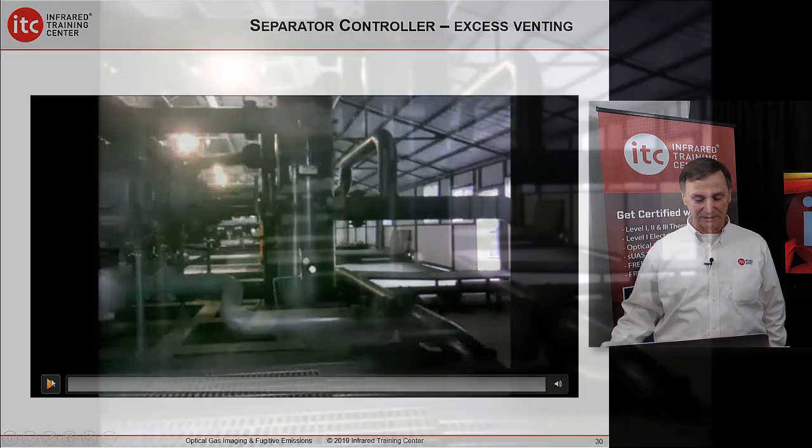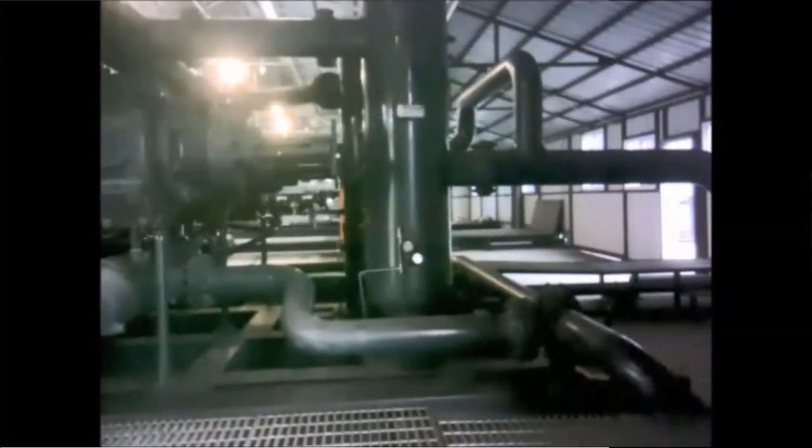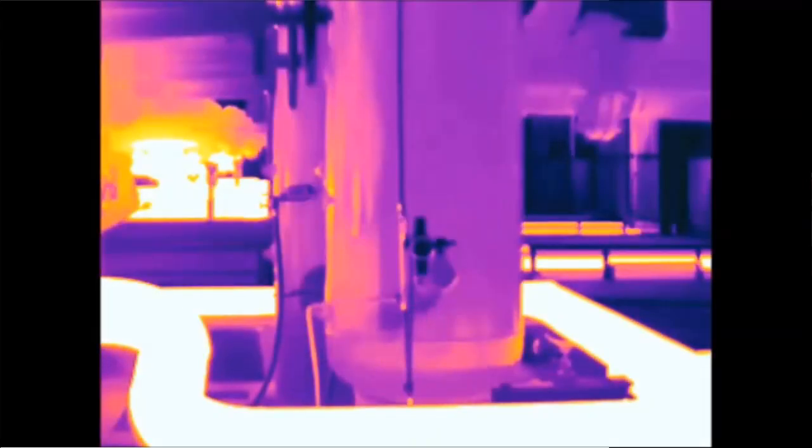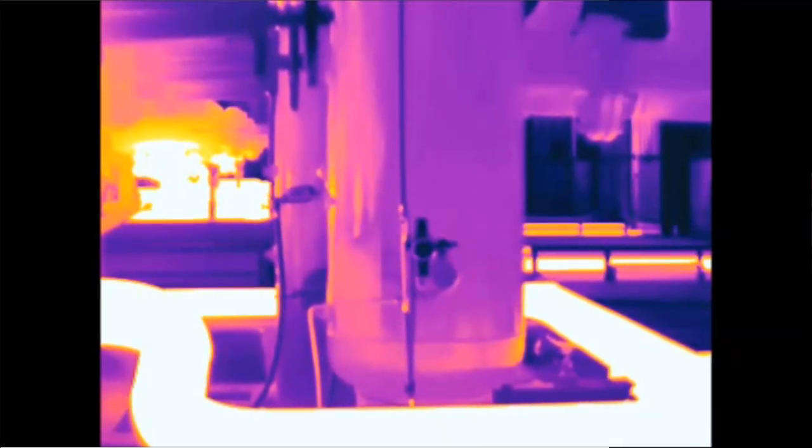Internally is a compressor building. This is a separator, and that's the flow control valve, which vents normally. They're designed to vent gas into the building or into the environment. That's what they do. But they're only supposed to vent gas when the valve is moving or when it's changing level, doing its deal. And this was venting continuously, so that was a problem.